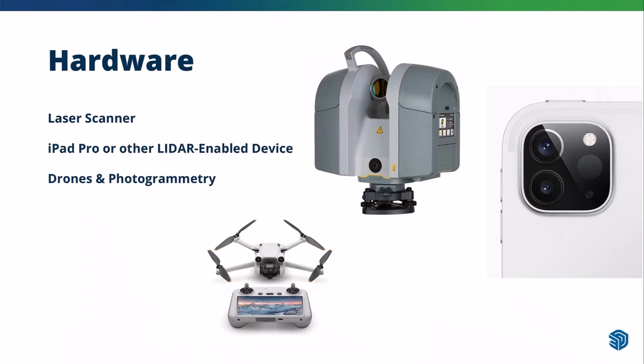Then there are drones, and you can use photogrammetry, whether you use photogrammetry using drones or terrestrial by just taking photographs, depends on the project obviously, but that is another way to do it, where you fly around something, take a lot of photos, and then process the surface of that building or whatever into a mesh or a point cloud, and then work off that. That could also be anchored back to GPS coordinates and made reasonably precise that way. And for larger projects, that is very likely a tool of choice.